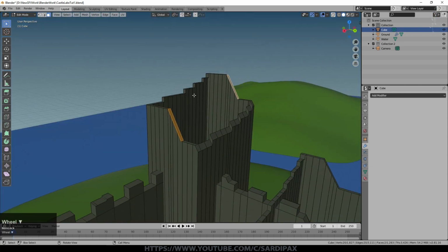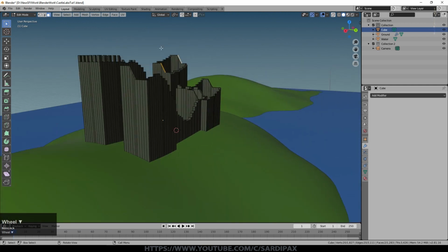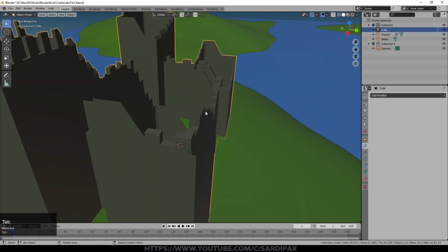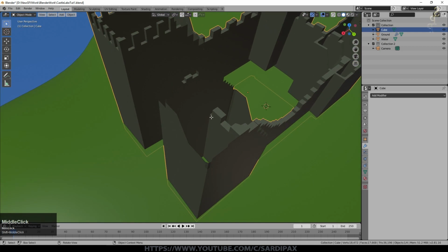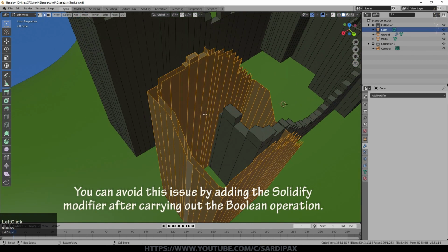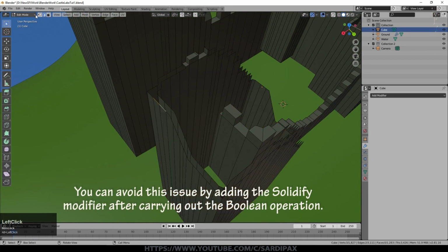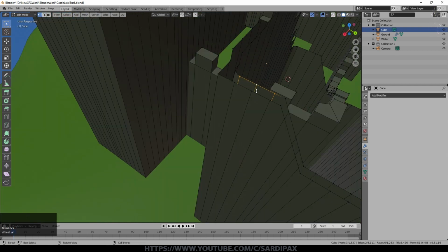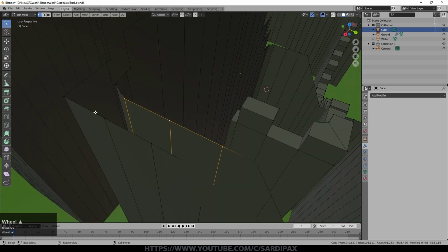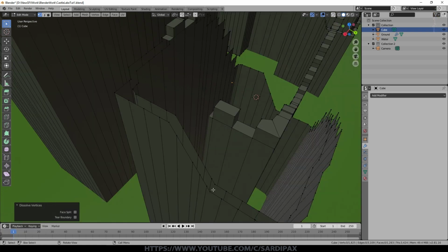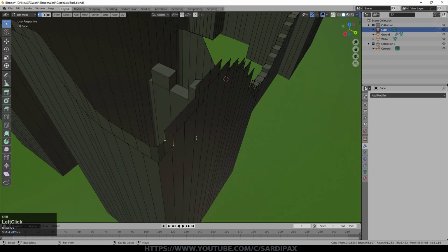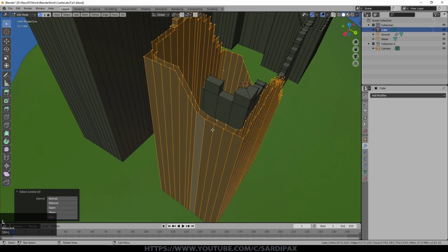Bearing in mind we're seeing this from a significant distance, I put windows in mine as well, and you will find in some areas you've lost the tops of the walls. So if that's happened, you'll need to select the edges and fill them again, but you'll probably have some odd vertices here and there causing problems. So I just went round, any like that, just dissolve them. Once they're all removed, then you'll be able to select all your vertices and fix them.